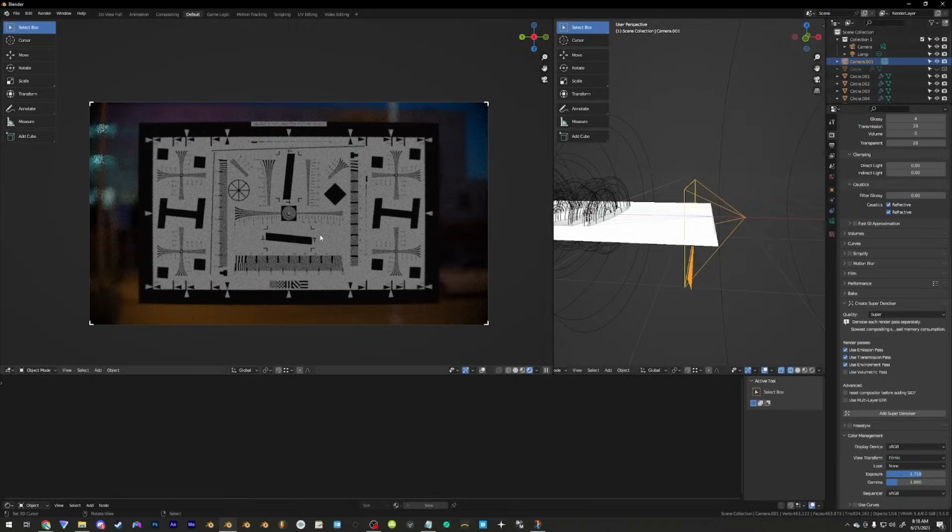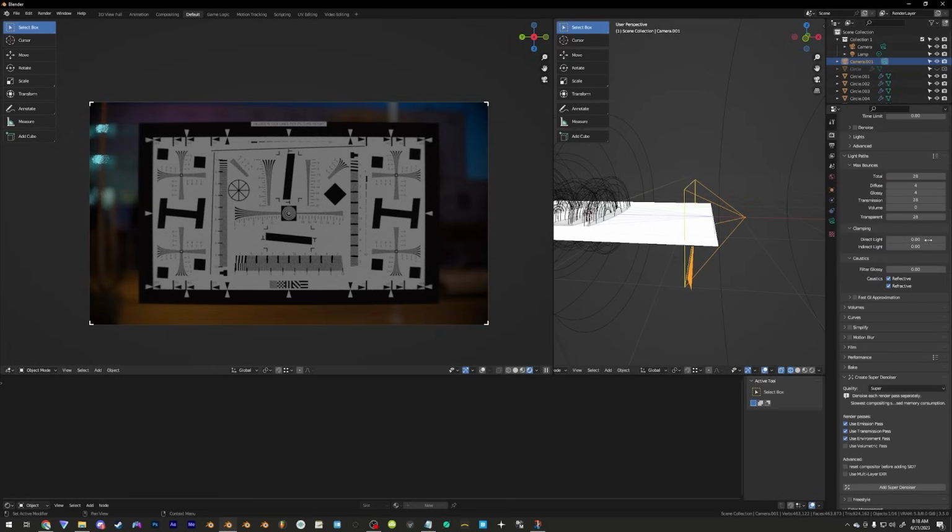Now we have our lens. We have our patent that we have copied, and it creates beautiful background bokeh. However, there are a couple of technical details that we need to discuss. Clamping is the first one. We do not want clamping. No clamping. If you clamp your light like this, it will dim your highlights, which will reduce the pleasantness of your render and potentially ruin it. We don't want clamping there.